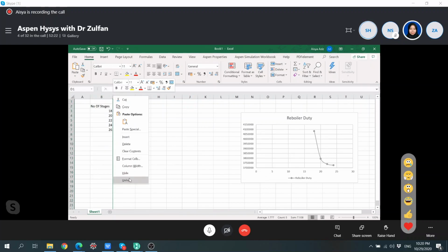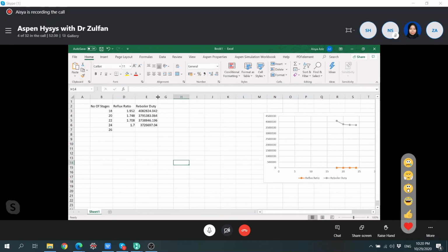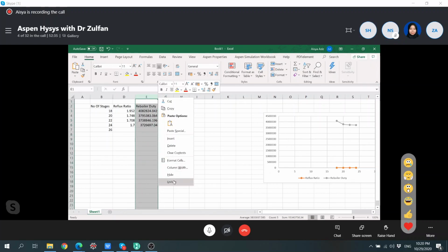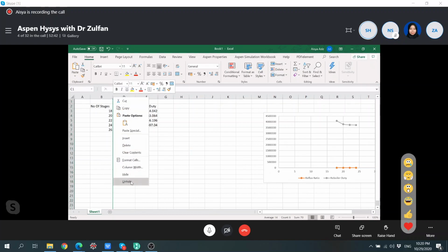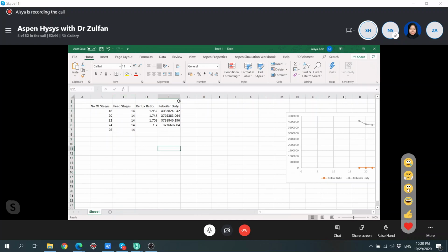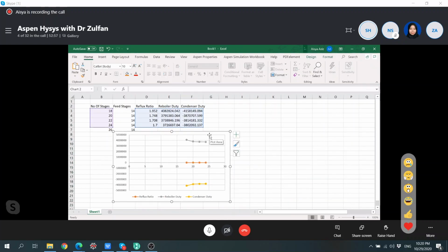It's a very strange unit, but anyhow, that means to get that kilojoule per hour of energy, assuming 100%, because if we say that this is coming from the steam, and this steam is going to be condensed in this reboiler to provide the heat, right? And then if you don't know, you have to check the bottom temperature of the column. It's about 170 degrees C. Yeah, it's 167 degrees C.